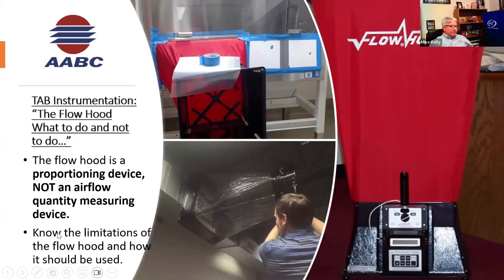It's a quantity measuring device, but the accuracy, there always needs to be some sort of factor put on, whether it's a 1.0, a 1.1, a 1.05, a 0.85, a 0.95, meaning we got 100 CFM, but when I take the hood down, we got 105 or 110, because when we put the hood up, it restricts flow and air comes out of the outlet next to it. Again, they're proportioning devices.